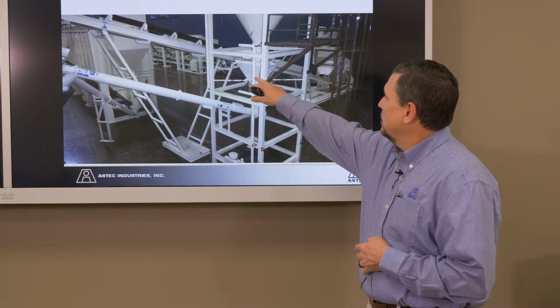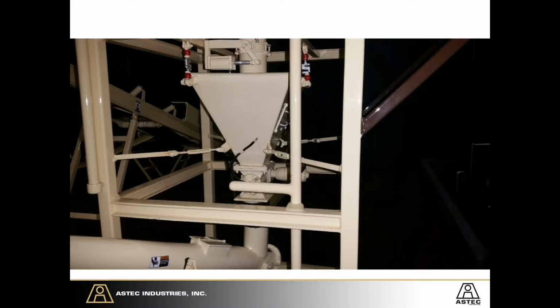And you can see here, this is what we have on a weigh pot. Now, not only are weigh pots pretty popular, and probably that's what you see on most mineral filler systems, but there are impact plates and a few other devices that are used to meter dust. They are weighing devices too. So if you can use that, that is the best way to look at the weight of mineral filler.